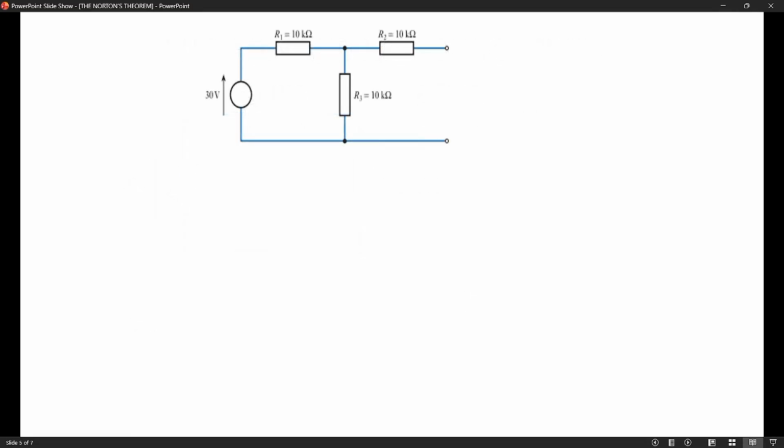So at first we must use the voltage potential divider rule. In my last video I taught the voltage potential divider, and it's very simple. This is how we go about it. Here V is the voltage source, where R1 and R2 are here. We don't consider R3 because in Thevenin's theorem, the circuit is an open circuit.